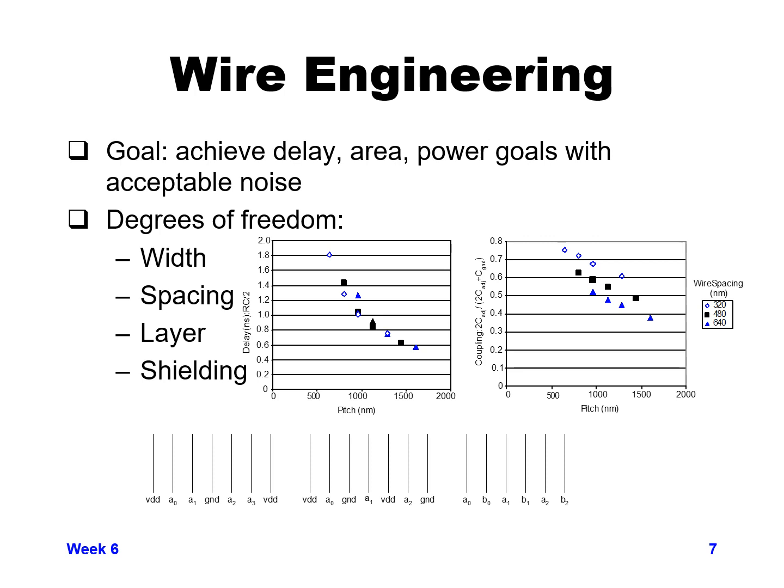The middle set of tracks shows where every other wire is a signal track and every other one is either VDD or ground. So we have VDD and then A0, then ground, then A1, and then VDD again. So in this case, this is what's called full shielding.